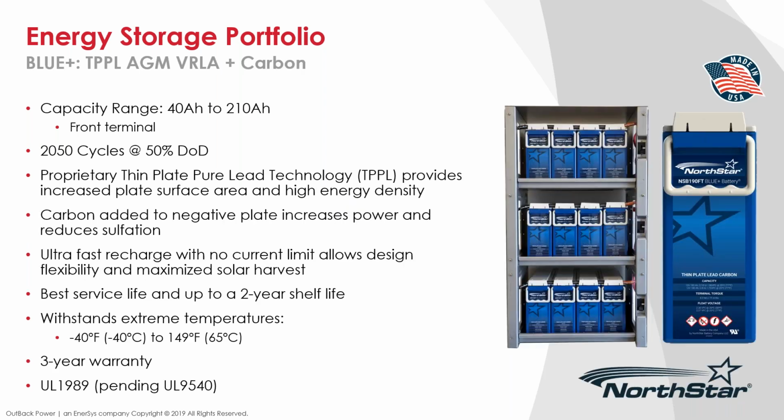The Blue Plus, again, it's the thin plate pure lead, but it also has carbon, and the carbon is at the negative plate, so it increases power and it reduces the sulfation. And the other thing that's cool about that is it likes the partial state of charge. So if it doesn't get fully charged all the time, it's not only not a penalty, it can actually increase cycle life. So it really likes partial state of charging. If you go below 50% depth of discharge, you are going to start losing cycle life though. So you want to keep it between that 50 and 100%. It's got 2,050 cycles at 50% depth of discharge.